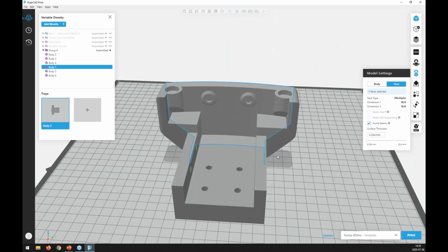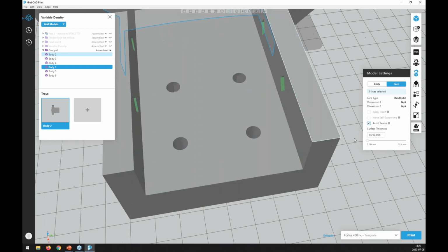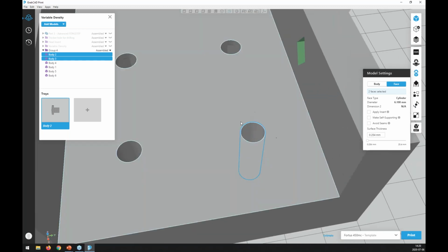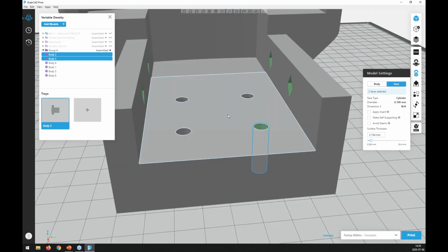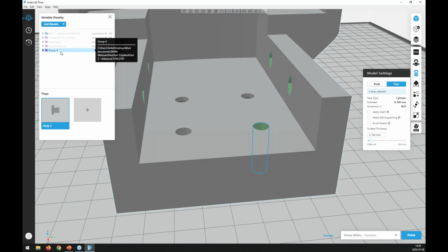What we can also do, when we have this option, is increase surface thickness if we need to. You remember from the first slide, I showed you that for drilling the hole, you probably want to have a little bit of material around it, not to drill into the sparse section of the part. So you may see from the slide that I used 2 or 3 millimeters around the part. We can just type this value manually, or we can use the slider because it increments according to the slice thickness, and have our hole thickened and prepared for drilling.